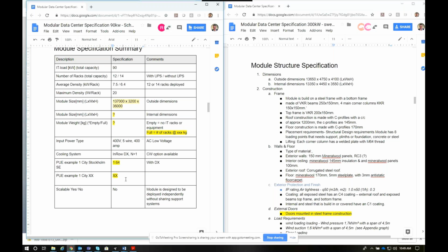Yeah, a couple issues. One, the module that we have spec'd out is a standard old DX. So if you were to worry about the peak current draw, with battery charging and junk like that. All right. So the 90 kilowatts that you're calling it is kind of a steady state thing. It's just the IT load available for the customer. So it's actually a 100 kilowatt UPS. It's a bigger panel to cover the DX units. You got house loads, everything else.